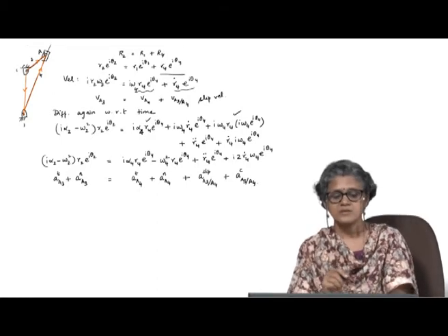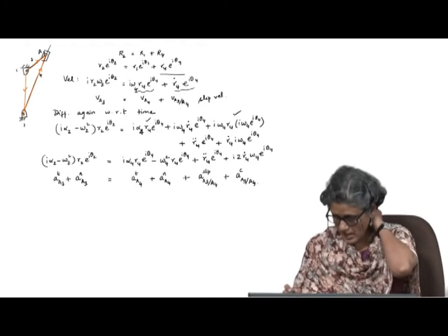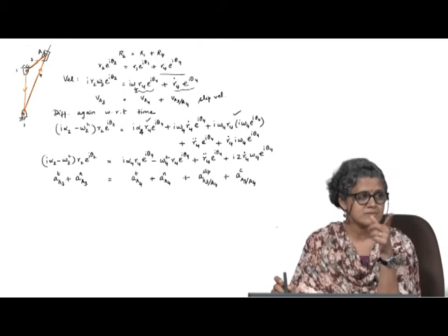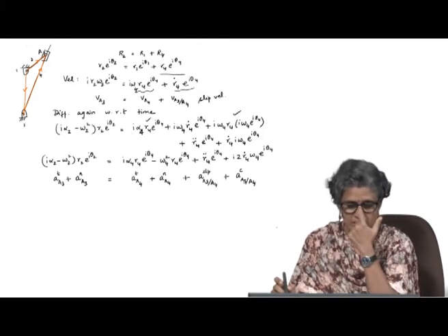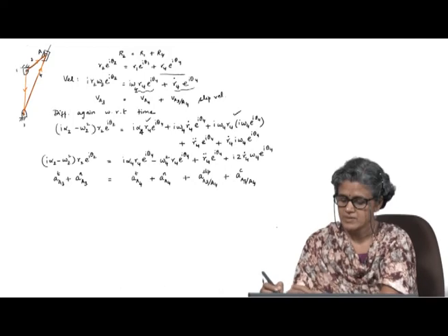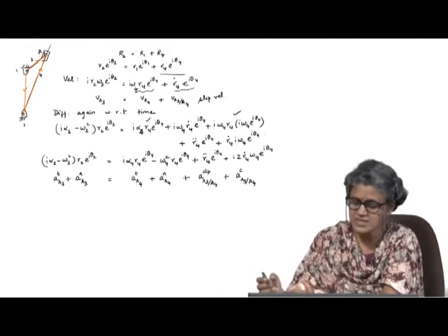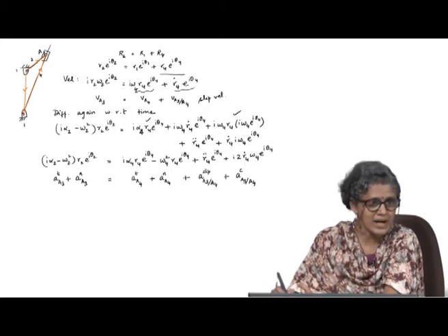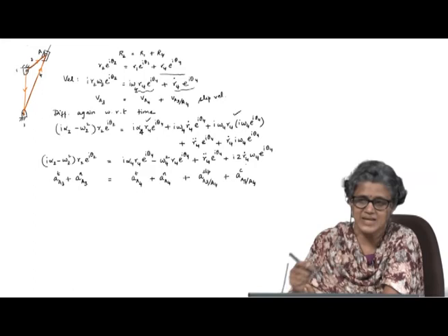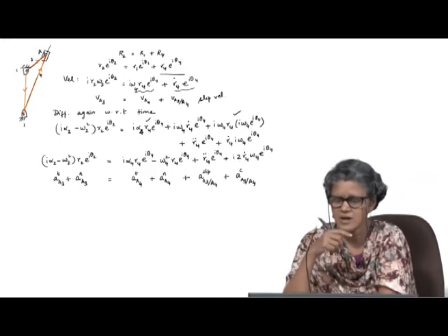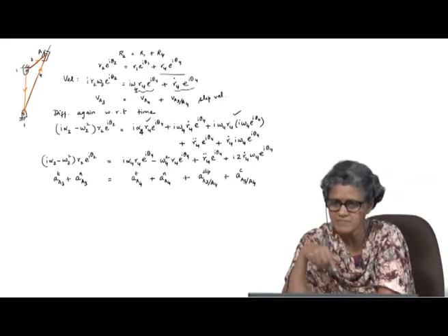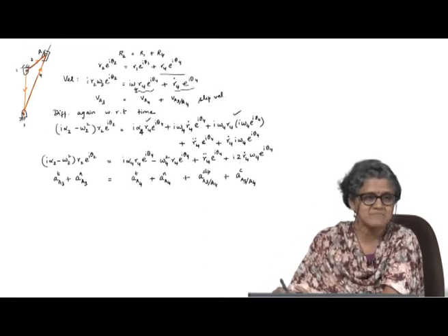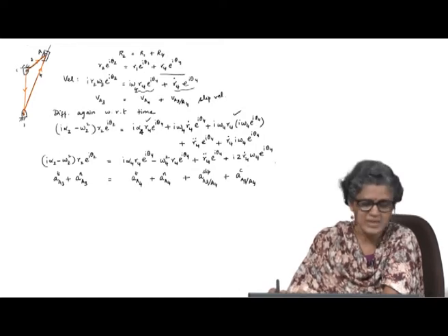So, the Coriolis acceleration appears when you have a rotating slider essentially. You have here omega 4 and R4 dot. They are sliding with respect to a rotating path. So, when you have both of those, you will have this Coriolis component of acceleration.